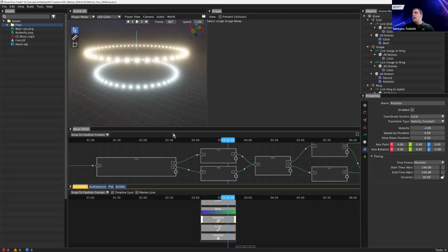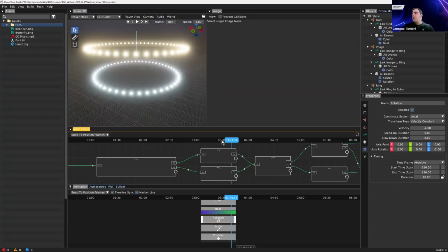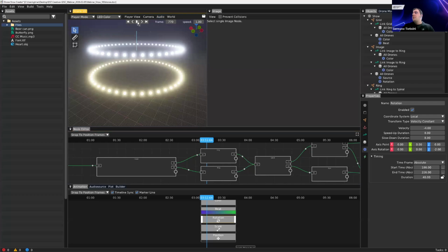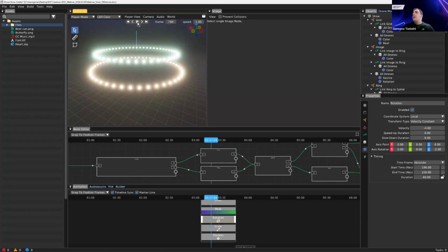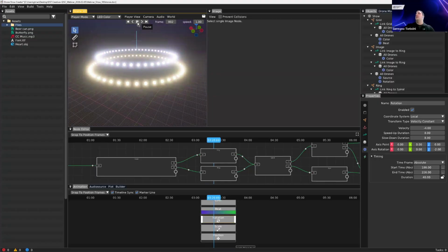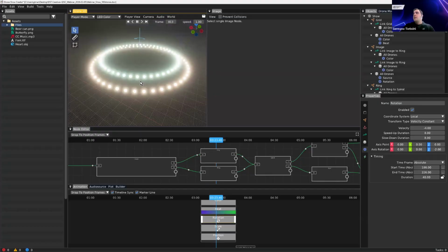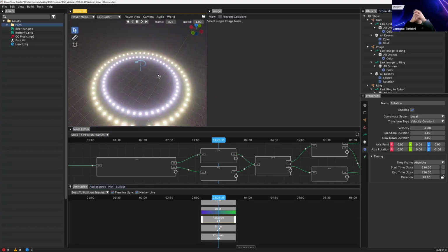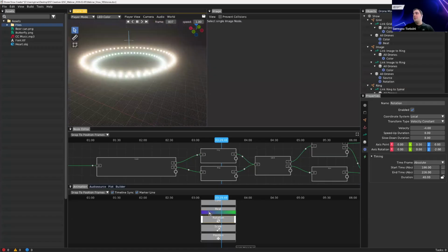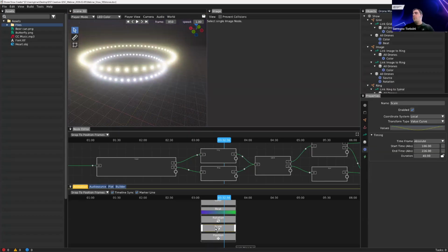Here, what's happening? If we look at the ring which is now lower, which began higher, let me unmute the music again because it's just going to get in the way now. The drones are rotating along that central axis, so they're going on in a file. Now the whole formation is also coming down and the other one going up. Finally, their whole circle is shrinking to a smaller radius so it can pass through the bigger ring without any drones crashing. So here we see rotation as the drones rotate around their axis, scale as they shrink and then go back to their original size, and position because the whole formation, the whole shape, the whole node is going vertically down.